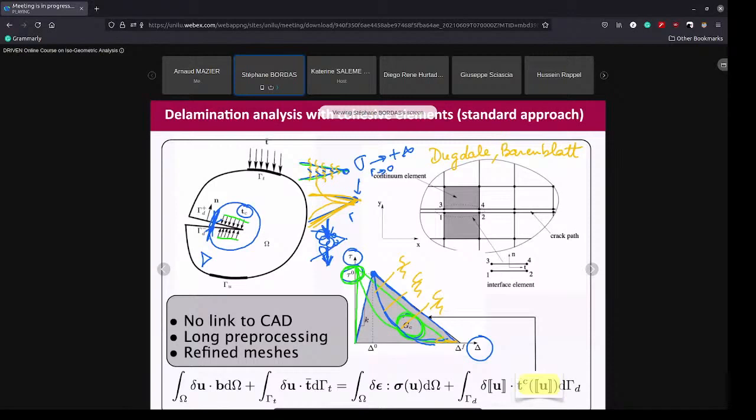In order to do that, well, you recognize this weak form. This is the body force. This is the traction on the Neumann boundary. This is the divergence of the stress. So basically, what we had before as grad U, grad W. This one here is the W U prime, and this one here is the B W. Right. So this is the equivalent in the notations that we had before, so that you can recognize it.